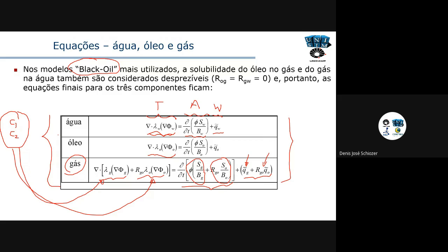We're going to study here just the basic equations for the black oil, which are the equations that are in most of the black oil commercial simulators. It's exactly this one, okay? So these are the most important equations you have to understand in these two classes, because it's very important. We are going to solve these equations for all the blocks in the reservoir. Okay, so if you have, for example, 1 million blocks in your reservoir simulation, we're going to have 3 million equations to solve, because we have to account for the water mass balance equations, the oil balance equations, and the gas balance equations. Okay.